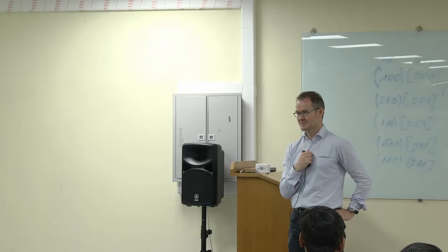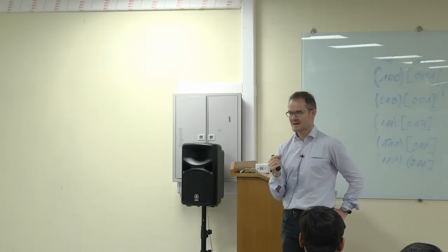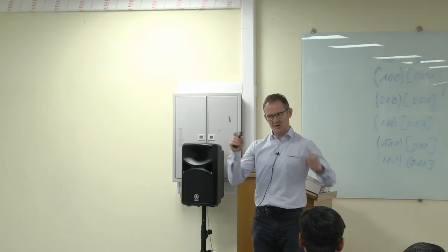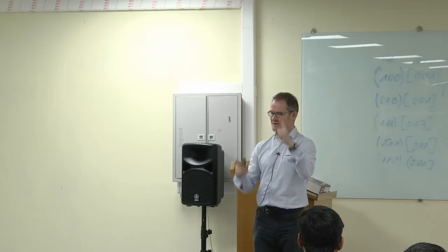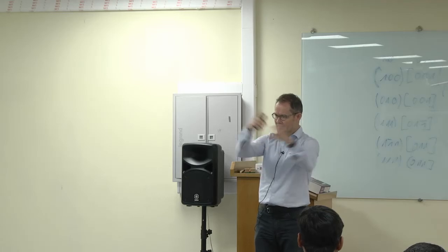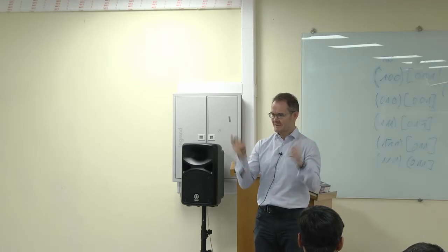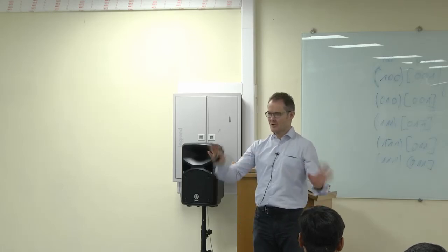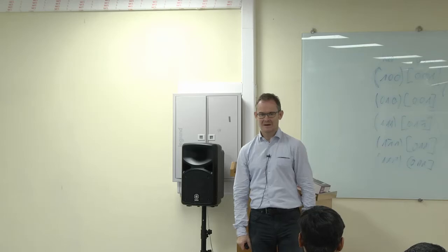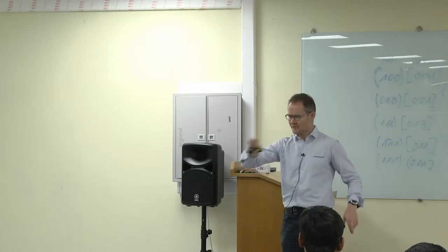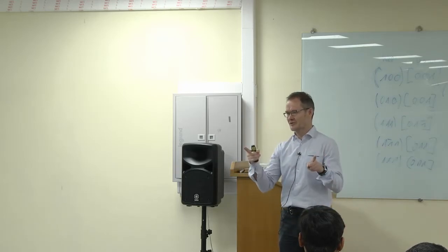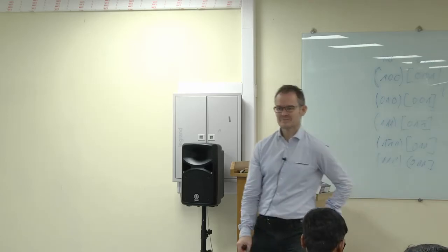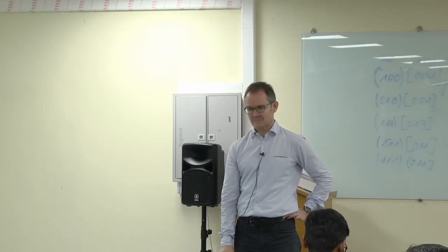Misorientations I will speak about a little later. But it's a very valid question. In Rodriguez space, you can almost go with a ruler and measure, okay, if it's 2 centimeter distance in my drawn space, then it's everywhere 20 degree misorientation. But in Euler space, it cannot be done like that. And the best is, also for Rodriguez space, not fully valid, the best is you calculate the misorientation.